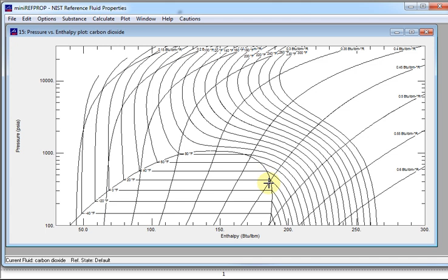I'm going to pause right now, and I'm going to hand you a print out of this diagram. And as a design engineer, you need to explore thinking about having two heat exchangers, a compressor, and an expansion valve. And you want to explore how high a pressure you push it to. Because you have the low pressure side. Let's say it's already dictated. The low pressure side is 300 psi.